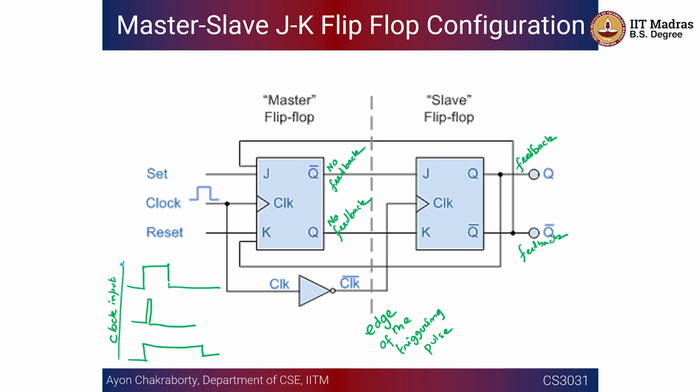So in our common sense, if we are using the JK in the latch configuration, the wider pulses are not favored, because this amount of time, let's say this amount of time or this amount of time, is going to lead to uncontrolled toggling, okay, for a JK latch configuration.